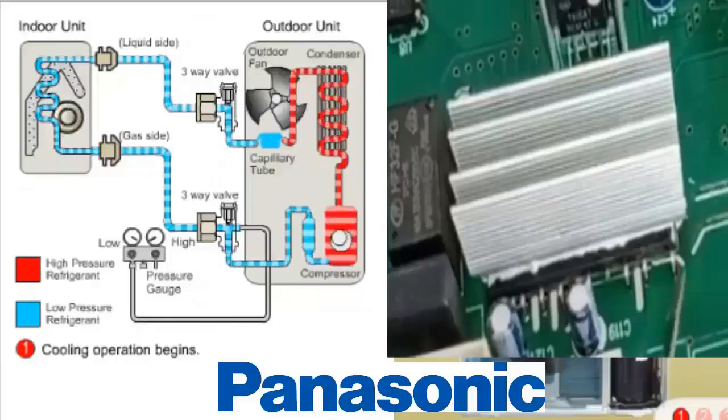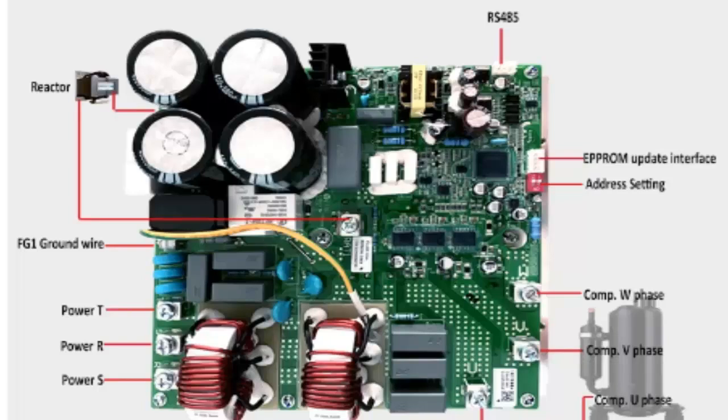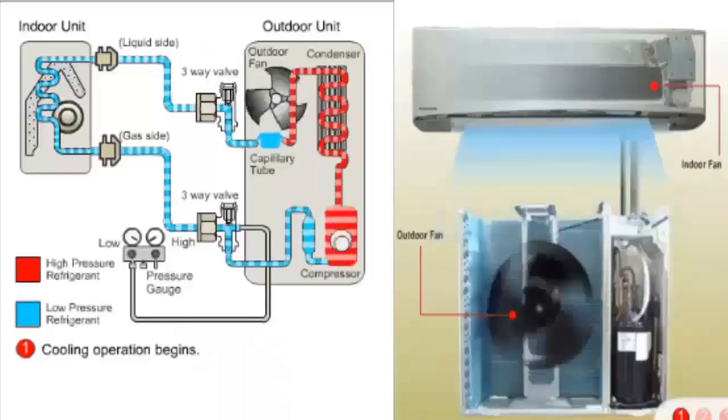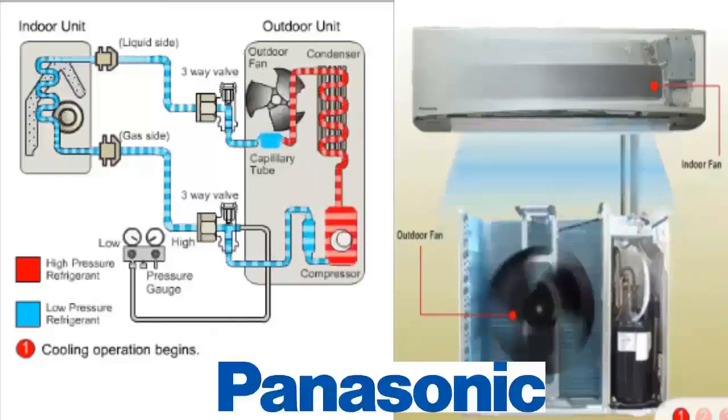Error code F99 associated with the DC current protection system, caused by possible issues such as compressor jamming, transistor module failure, malfunction of the current sensor on the outdoor unit board, or compressor winding resistance below normal. Steps to resolve these faults.